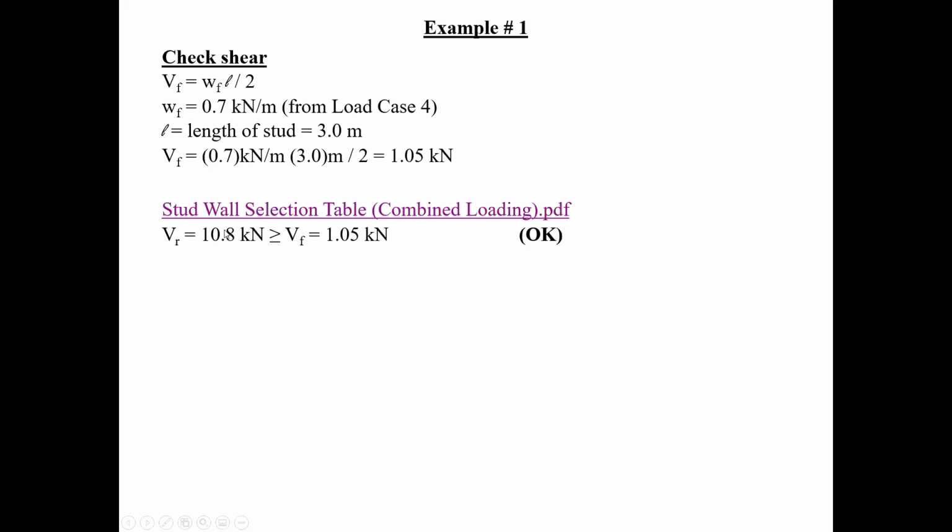What's the last thing we have to check for? Deflection, exactly. Okay, serviceability. Let's call it serviceability, and therefore in this case we have to check for deflection. Now, we know that 99.9% of the time when they build an exterior wall, there's going to be gypsum on the inside face of that wall. So since there's gypsum, what's recommended is that you limit the deflection to L over 360. So that's something you should know.